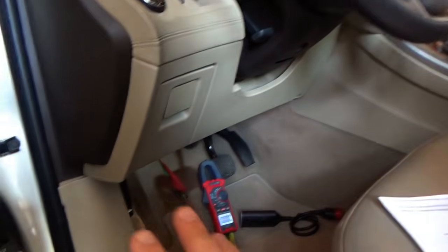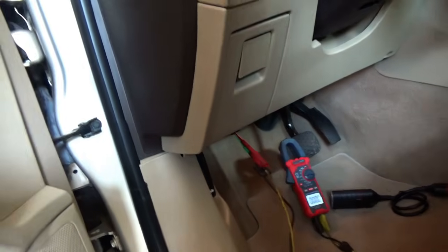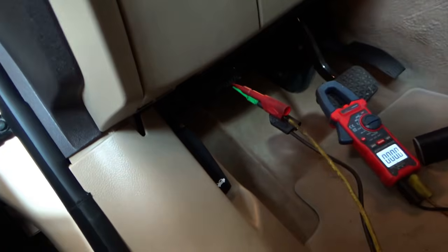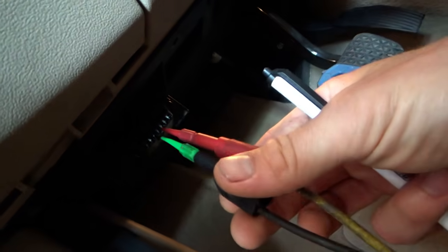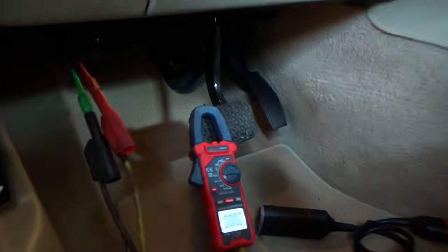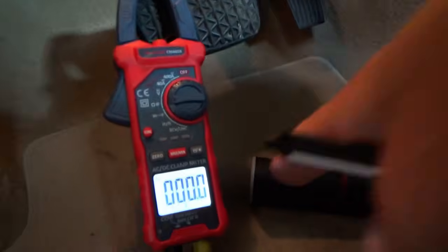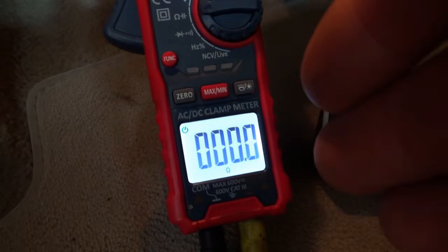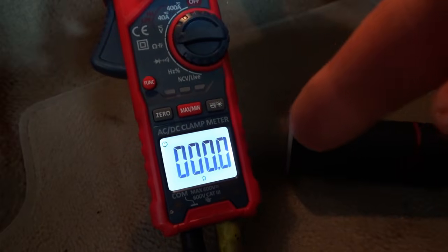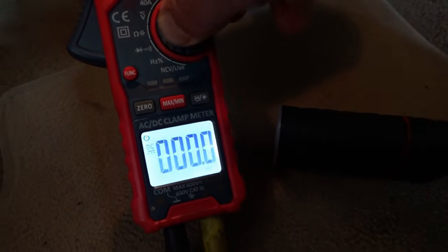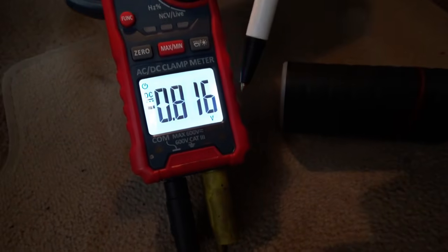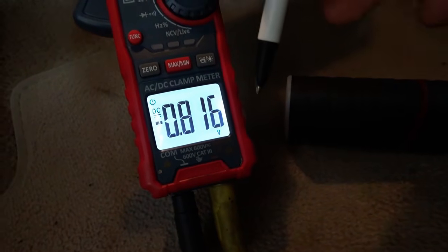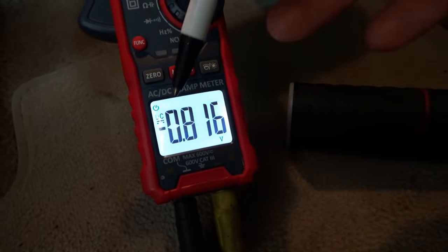So the car's off. It's asleep, but we don't have the battery disconnected yet. Let's see what readings we get on pins 12 and 13, just across pins 12 and 13 on the ohm meter scale. Look, it's showing 0.0. So are these wires shorted together? Be very careful about this measurement. What is the voltage across these pins? 0.8 volts. So the system is either not asleep or there is another problem.